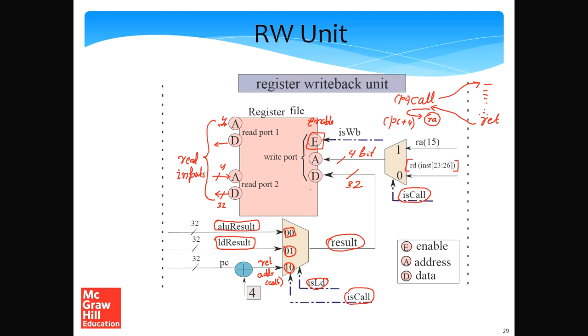The detail is enough to actually implement this in actual hardware using a hardware description language. So what I would suggest is that readers can take a look at Logisim. Logisim is freely available on the web with an open source license. Readers can take a look at it because it's very easy to use, especially for first timers. They can design this circuit on Logisim, and this circuit will work as is shown.